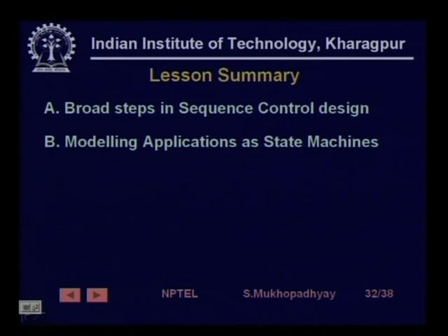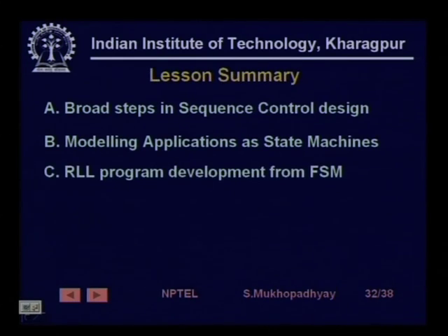We took a very simple industrial application like a stamping process and built its state machine, and then we have shown how, given the state machine, very mechanically you can structure your program and then write the transition logic, the state logic and the output logic, and we have seen that this is very much expected to lead to error-free programs.